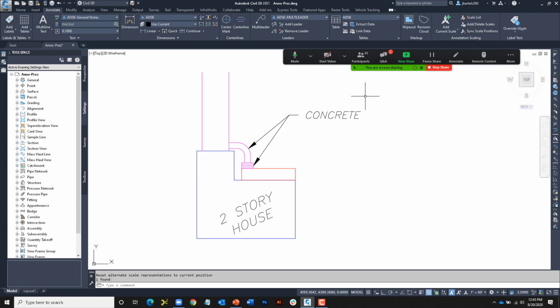If I select that, what it did was it pulled all the variations up to match the location of the current one. Now, if I wanted to independently move these here in Model Space, I did it through the Viewport before, but let's say I'd like to move that 30 scale one down. If I just change this to 30, there's the 30 scale variation. I can click. Even though I see that ghosted version there, the grips apply to the current one. And we've seen how we can turn off that ghosted version if we want to.